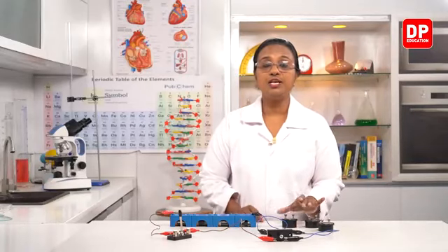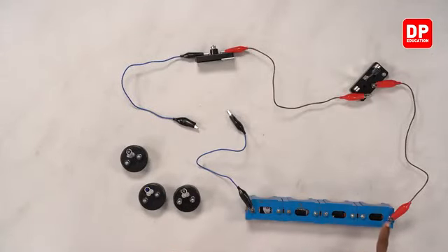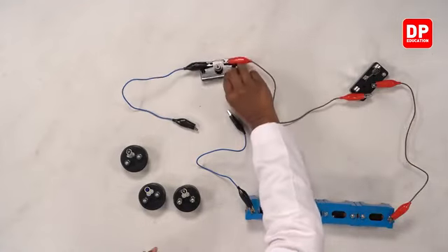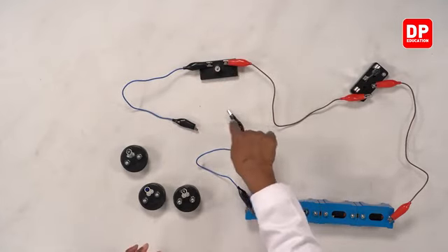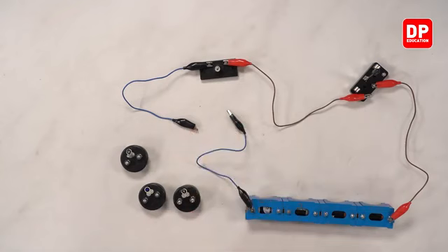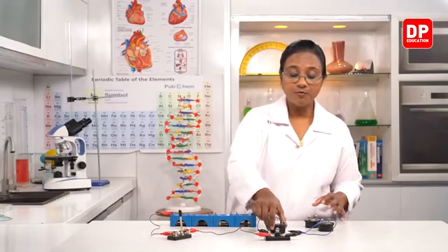So I will use the 5 ohm resistor first. If you look at it, I have connected 4 dry cells, 4 batteries. So they are connected in the correct manner, positive, negative terminals alternately. So the potential difference is there. Then the switch is connected there, and thereafter you can see the bulb that is also connected. So between these 2 terminals, I will be connecting the resistor. First, I will start with the 5 ohm resistor.